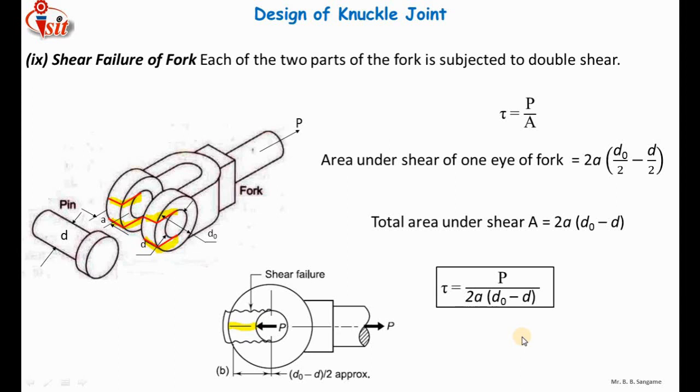Remember one thing, the induced shear stress should not be greater than the permissible one. The permissible shear stress is given in the problem, and the induced shear stress we have to calculate. If it is less than the permissible one, then our design is safe. If it exceeds the permissible shear stress given in the problem, then the design will not be safe.